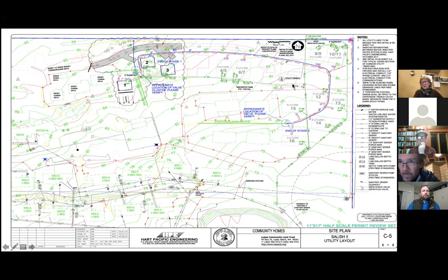And you can see right here it says 2-inch FM, which is a 2-inch force main. And it meets this 3-inch force main here. Now, you can't very well develop this area right here and have your septic stop, right? You've got to carry it all out to here, basically into this primary force main so it can travel all the way to the plant.